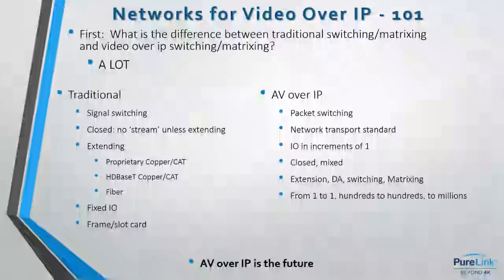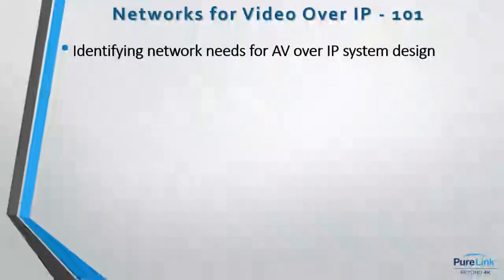I can check the complete health of the encoder and decoders over the network, but I can also detect my source. I can check that there is a source live or not. I can determine the resolution of the source, the audio format of the source. And on the other side, on the display, I can check, is there a display active on the output of the decoder? And I can also grab the EDID table from that. And in an EDID table, I've got manufacturer's information, I've got preferred timing and all that stuff. From a system maintenance, support, management, that's very powerful.